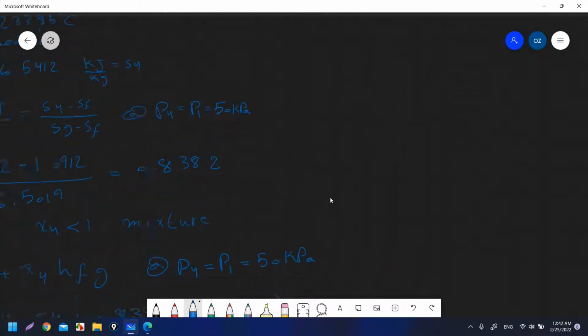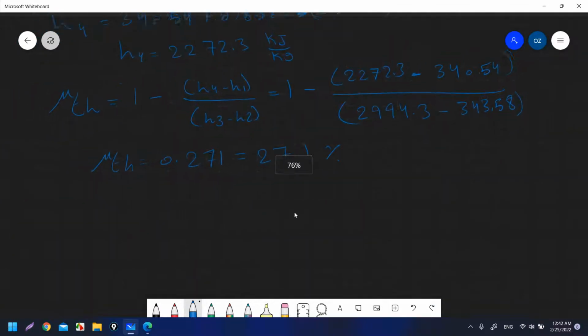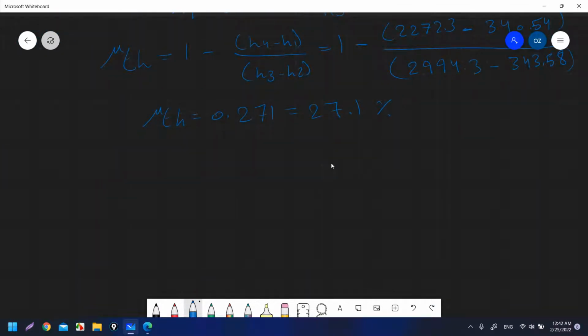Okay, so let's find first the work net in kilojoule per kilogram, the small w. So W net is equal to the work turbine, sometimes written WT, minus work pump in, equal to Qn minus Q out. So let's solve first with this equation. We already found work pump in at the beginning, but for work turbine out, let's find it.